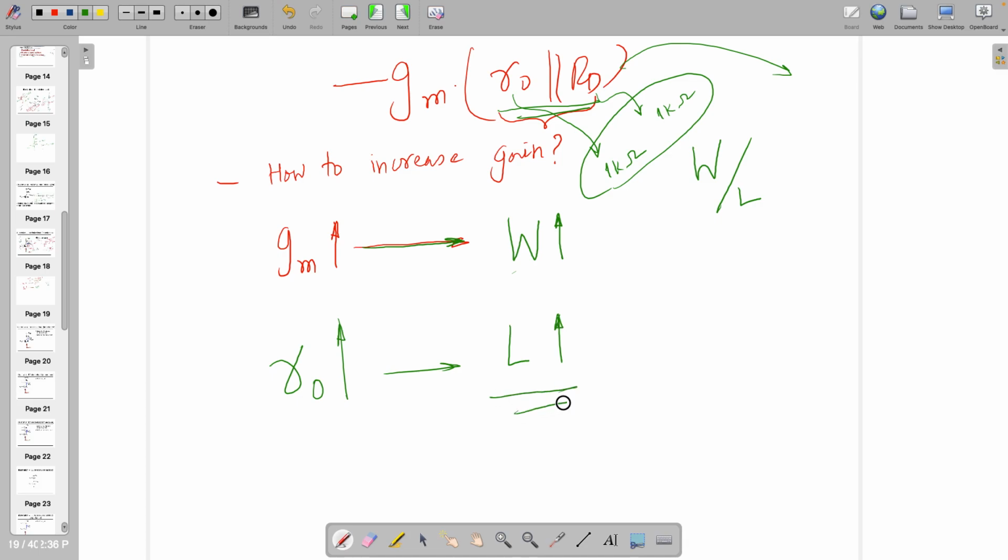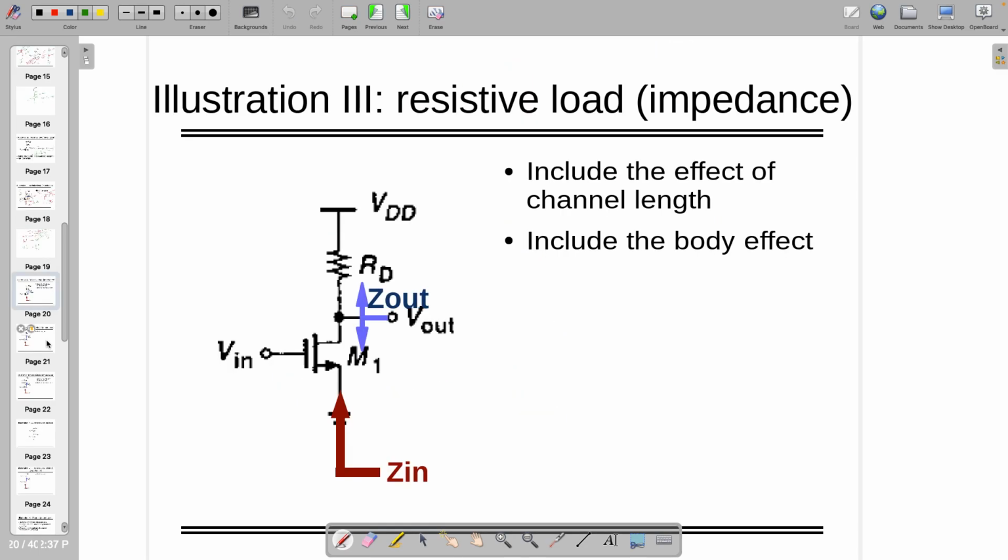As you are increasing L, it is decreasing the bandwidth. You might have achieved gigahertz, but because of L, bandwidth will reduce to maybe megahertz, right? So you have to choose these things very wisely. Do not go randomly. This is what I would say. But this is the way to do it. Maybe with time, when you are going to design some amplifier, you will learn what to touch and what not to touch. So there is no problem.